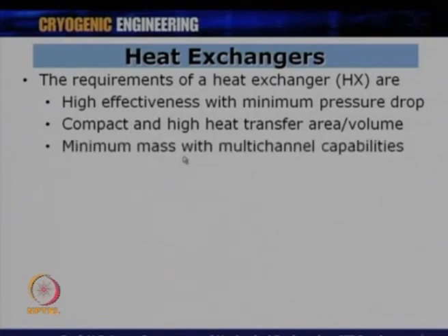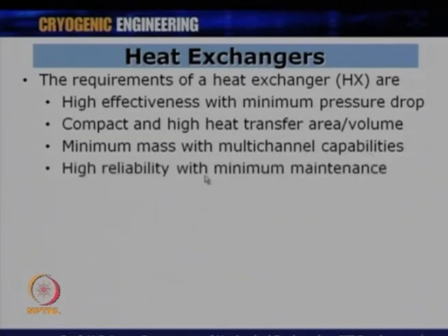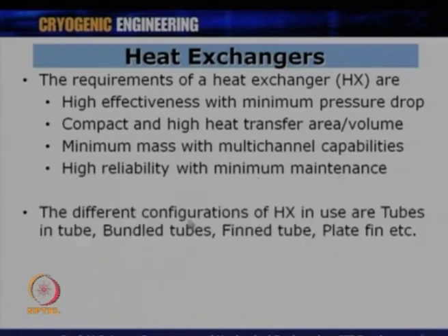We should therefore have minimum mass with multi-channel capabilities. If you have multi-channel capabilities, you can have more flow rates and more heat transfer area also. One should definitely have high reliability with minimum maintenance, and these are very general criteria. What is most important is high effectiveness and a compact heat exchanger.